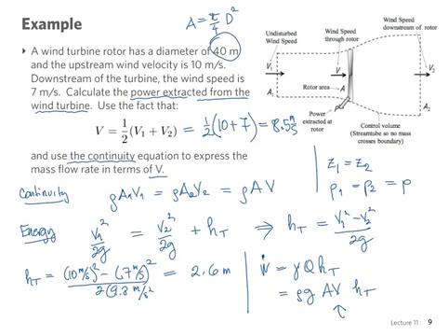So I didn't leave any space. Yes, question? Just air. Yes, just air. It's a wind turbine. So just air coming in, and we've drawn a control volume here that follows that streamline from the upstream point to the tip of the rotor to the downstream point of that particular fluid particle. Yes? So WT is the work that the air does on the turbine. The turbine is rotating and extracting power from the fluid. That is what has slowed the fluid down. So the fluid has less kinetic energy. That's why it goes from a velocity of 10 meters per second to 7 meters per second.